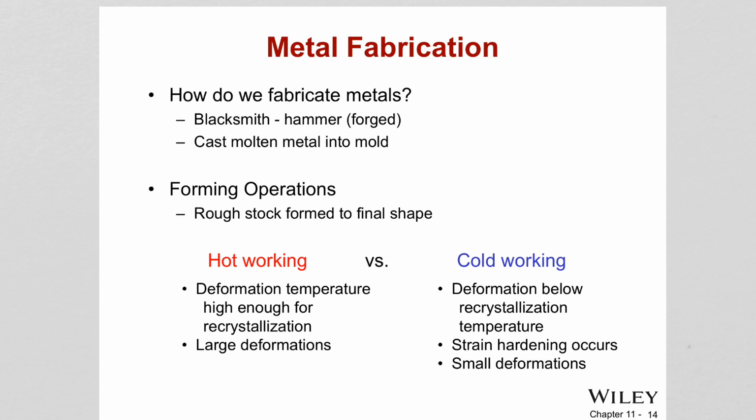But you can only do small deformations. For example, let's say you are trying to reduce the thickness. You cannot reduce the thickness to a large extent when you do cold working, because the material is not very ductile. Think about if you heat the material above its recrystallization temperature, you are providing ductility to the material. It is much easier to achieve large deformations without the material being broken.